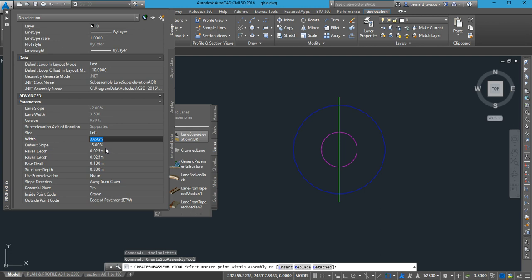Please, successful. Good. Now you have the thicknesses: pave 1, pave 2, base, sub-base. So these are the various layer thicknesses that you may have. Let's assume that we are leaving them as they are. Or, no, the pave 1, if you take, for example, an asphalt road, you may have the wearing course. So your wearing course will be pave 1. Your DBM or your binder may be pave 2. Then you have your base, then your sub-base. Are you okay? Now, if you don't have pave 1, pave 2, you just set the value to 0.